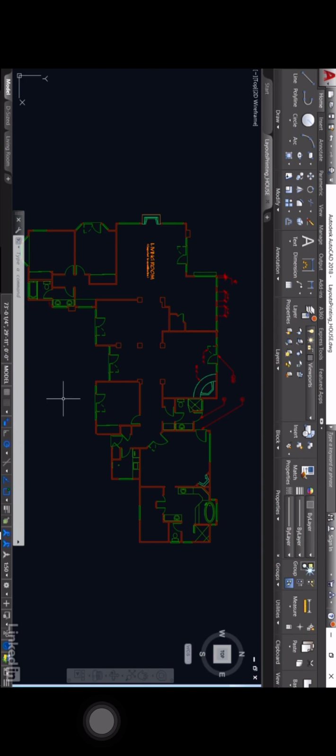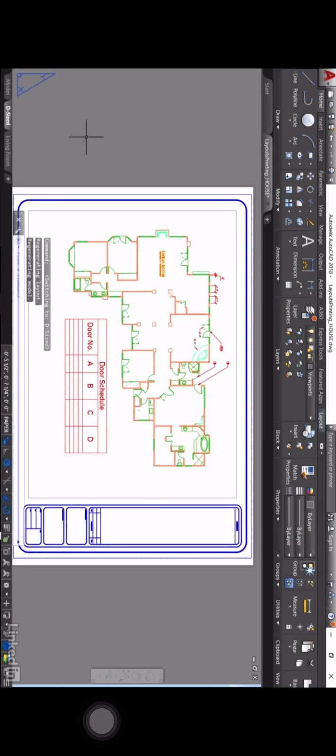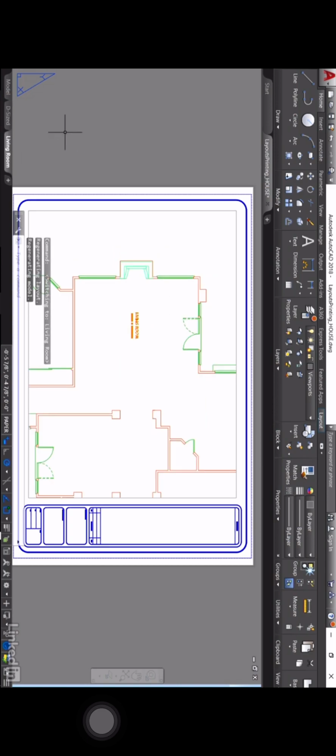Now, what we've got is, in this particular drawing, our model tab showing our plan of our house. We've got a little bit of annotation going on here and there as per the previous chapter. Now, if we go into the layout tabs, you can see that we've got a D-size sheet tab with an overall general arrangement view with a nice little door schedule table sitting in the layout as well. The other layout tab uses the same title block, but it's actually just showing us the living room, and the view in the viewport is different.